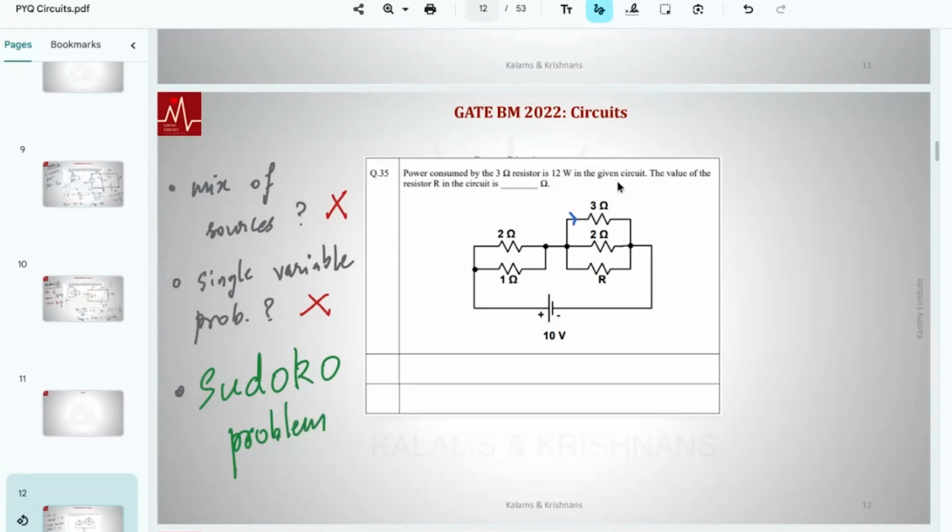This is 12 volts. So I know the current. I squared R is 12. So I suppose that is 2. I is 2. Agree? That is my step 1. My step 2, I know the voltage across. I'm not short circuiting it. I'm trying to find the voltage across that. I know that. The voltage there is just IR, 6 volts.